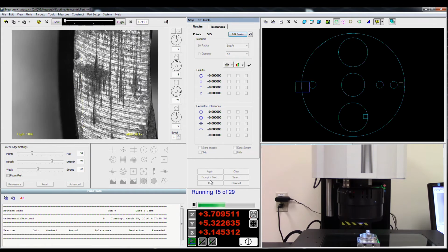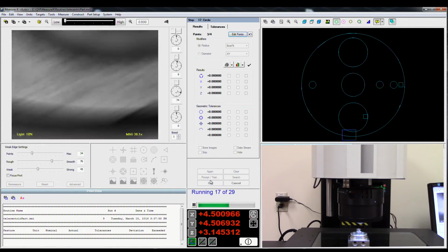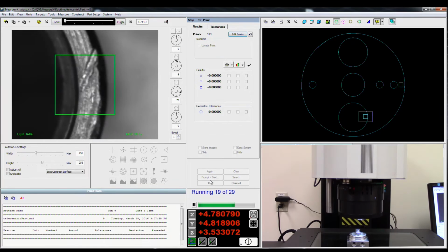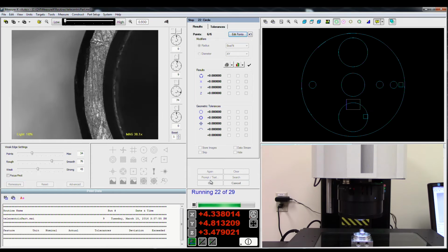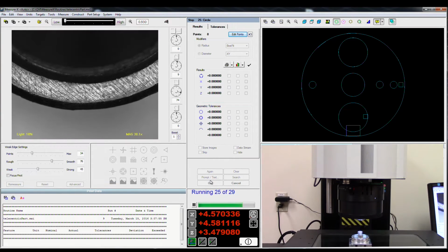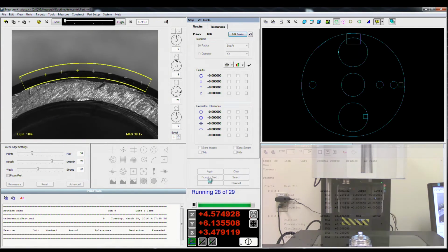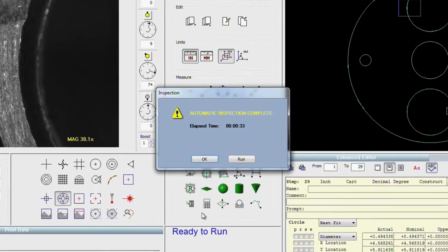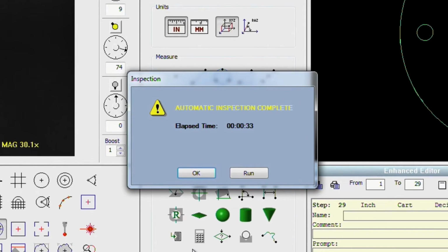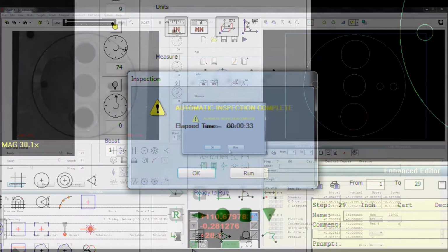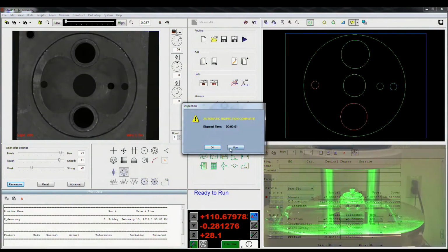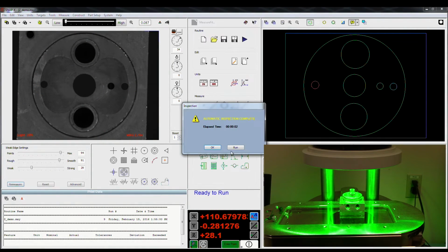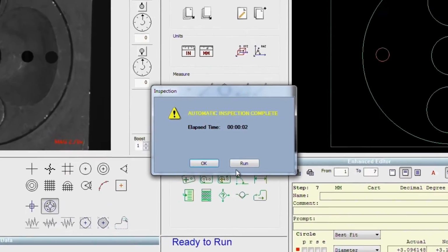Because the depth of focus is small, targeted features can be brought into sharp focus by analyzing the image as the optics are moved closer and farther away from the target to find the sharpest image, often referred to as autofocus. While this capability adds measurement in the axis of the optics, it is at the expense of time required to bring each targeted characteristic into accurate focus. When only XY plane measurements are required, a large depth of focus can speed inspection time significantly by not having to refocus on features not in the same plane relative to the optical axis.